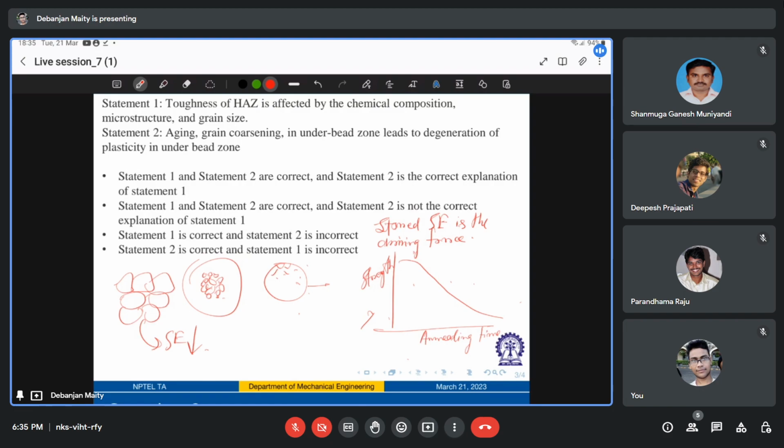In terms of the effect of welding parameters and process, both the size of the heat affected zone and the retention time above the effective recrystallization temperature. There is some question of what retention time is, I'm coming to that. Those increase with increase in heat input per unit length of the weld, right?